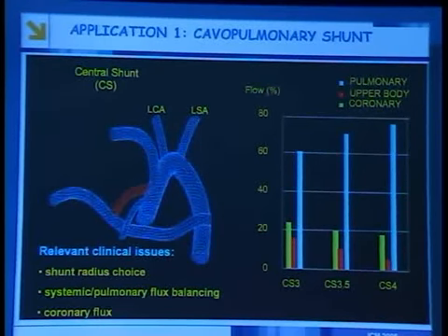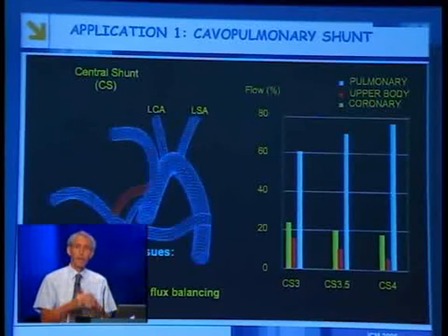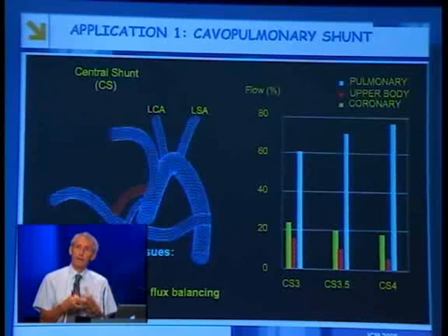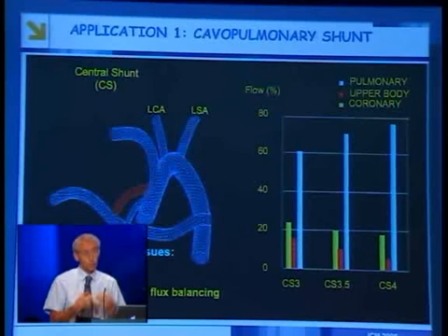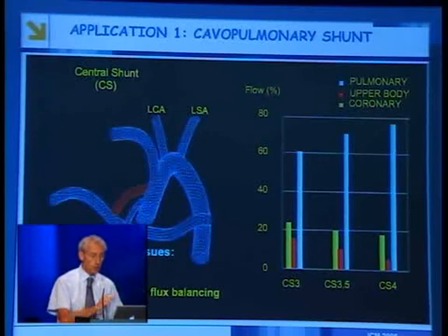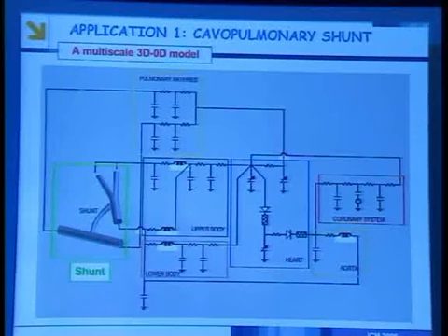There is no way to provide data to a virtual boundary in an exact form. So there is no way to guess which kind of inflow and outflow condition we can put there to be respectful of the actual nature of the problem. You know, if you work in fluid dynamics, how far the solution of the Navier-Stokes equation is sensitive to the inflow and outflow boundary conditions, and of course also to the geometry. So we have embedded this system, the shunt, in our geometric multi-scale problem. This is the shunt. This is the global zero-dimensional system to describe the rest of the circulation. So here is an interaction between a 3D and a 0D system, 3D Navier-Stokes, with a system of differential algebraic equations.